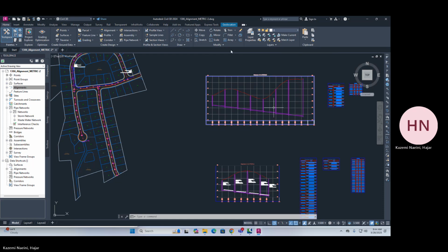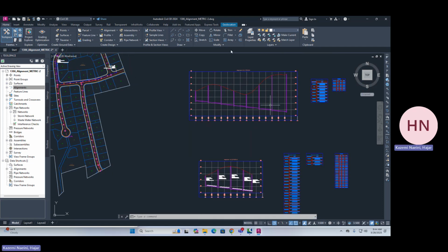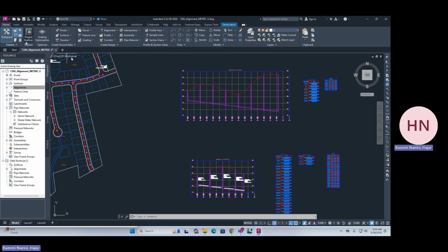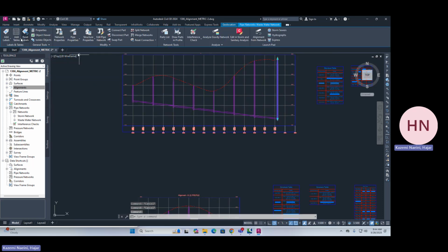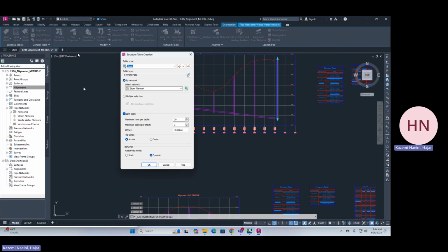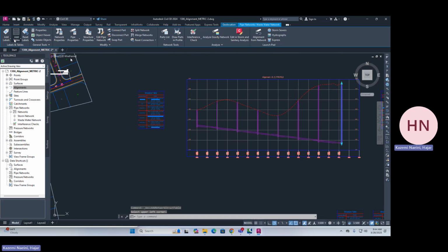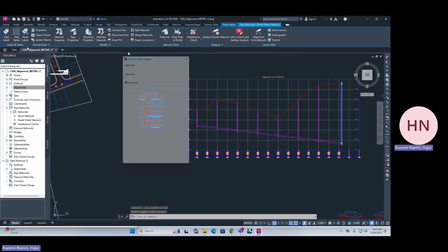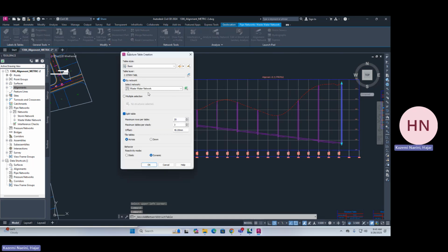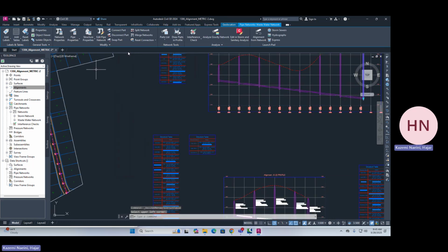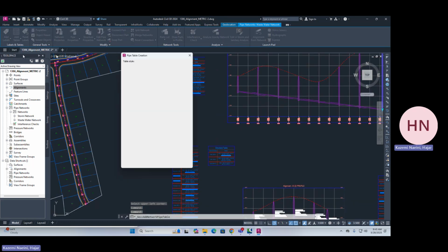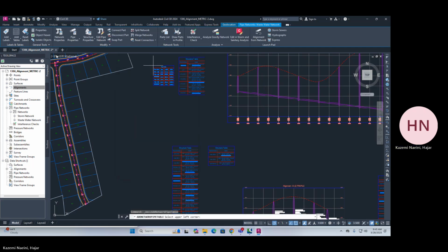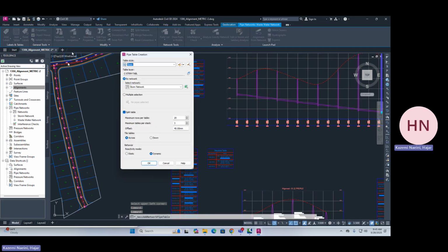Any question? No, the tables are wastewater or storm? The tables? You need to select one part, go to tables, go to add a structure. Once you should select storm network, create your network, then again go to structure and change it to wastewater. And for wastewater. And same process for pipes. Storm network here and go to pipe again and wastewater for pipe.